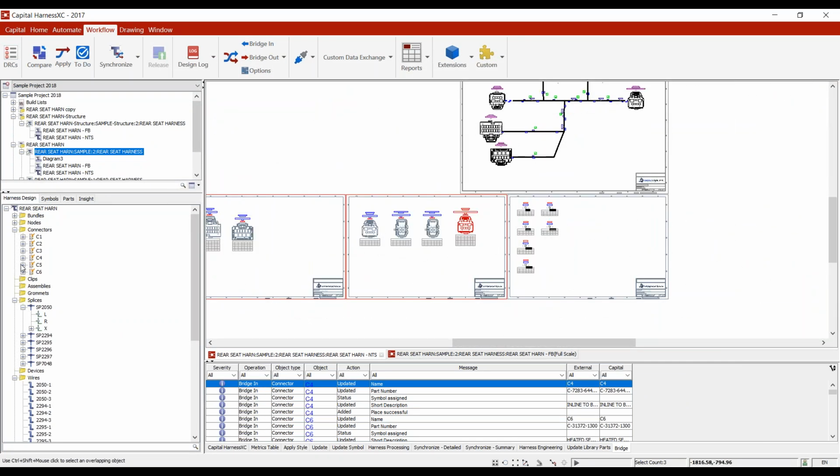And we can see that components were associated to the library components easily by looking on our left browser and seeing these orange check marks. So at this point, right, my connectors, I put in the connector part number in my from-to Excel sheet. So it mapped it to the library component. And so I get this orange check mark.